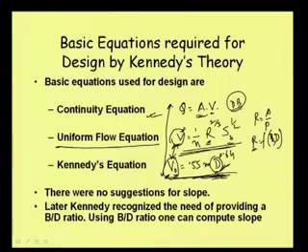Well, that means for that d value, we are not arriving at a position where our uniform flow velocity is matching, or becoming the critical velocity. So, that d will not serve our purpose. We will take another d, and again calculate our V0, and then with that V we will find the area, then again get B and D, that is the depth and width, and again check what we are getting in the field by using the uniform flow formula.